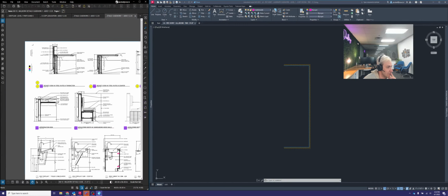There we go. And I always like to set my precision down a little bit. I usually go to a 16th just to make sure I'm not rounding at all, or at least try to minimize the amount of rounding that's happening. So let's go back to our room. And I didn't mention it, but I did click on this icon for length. We're going to use that to get an eyeball sort of guesstimate on what we've got going on here. Let's see if I hold my mouse, saying 2.25 feet. I would be willing to bet that's supposed to be 24 inches though. So we're going to run with that. Typically you want to match whatever they show you. So if they give you a dimension, you want to use that.